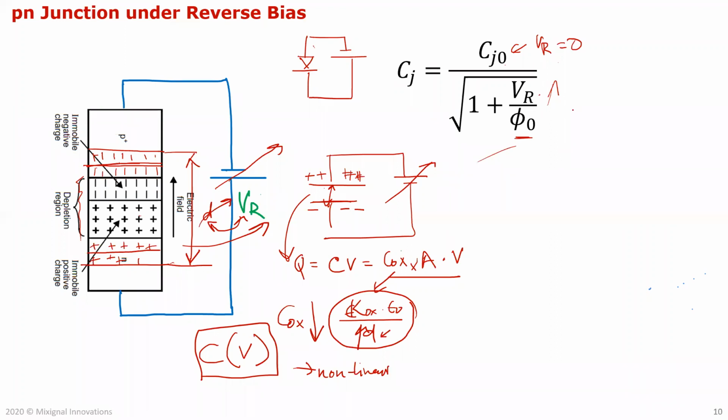This capacitance is becoming a dominant one for lower fine-line technology now, like 7 nanometer, because your gate area is so small compared to your drain area. For longer channel lengths, like 0.25 micron, 0.35 or 0.18, this is a smaller portion, but now it's becoming dominant.